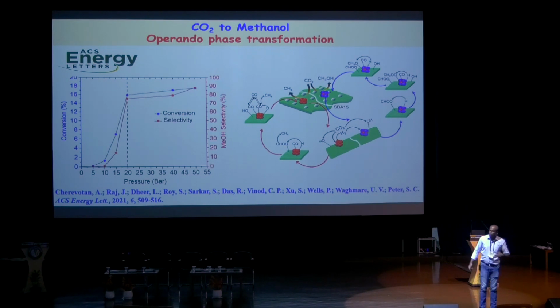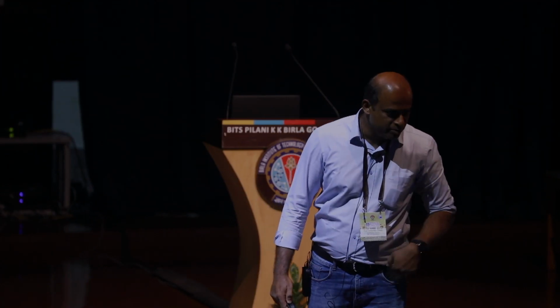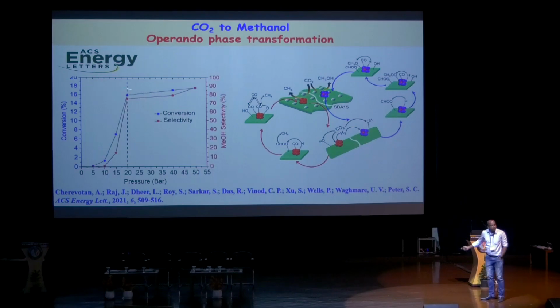If you go to methanol, one work we have done, Professor Bakmar is actually a collaborative partner, he did the theoretical calculations in that one. There is a plant in Iceland that manufactures methanol, I will show the plant, that is done by Professor George Olah, Nobel Prize winner, and Surya Prakash. The conversion is 22% of CO2 to methanol. This is a 4,000 ton of methanol per year production capacity. They use geothermal electricity, but they use a pressure of 300 bar. At 300 bar pressure, you need a lot of energy input.